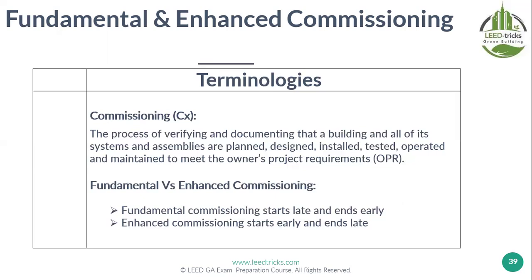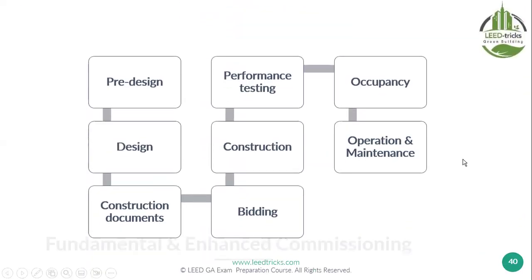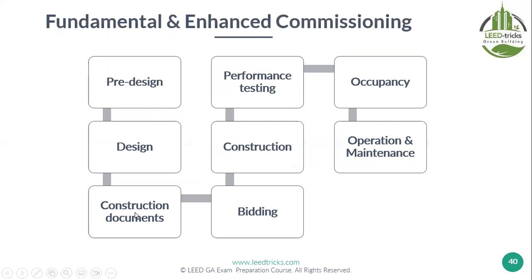Fundamental commissioning in LEED starts late and ends early. What? Starts late, meaning in the construction phase, or by the end of the construction phase. But enhanced commissioning starts early in the design phase. Before you conclude the design, you should have started enhanced commissioning. So it makes a big difference. So pre-design, design, construction, testing, occupancy, operation. When I say fundamental, you always start it during the construction phase, and so on, but during the design, this is enhanced commissioning.